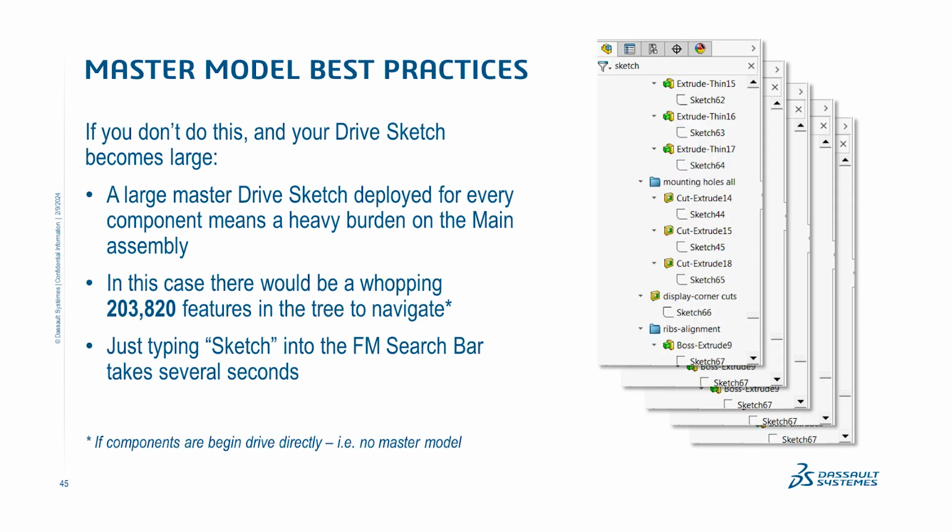The other thing about that is, if you do create that master sketch and use that as your master model technique, you have various parts in your assembly and they're all being driven by the master sketch. Well, there's a danger in that too: you're overburdening your assembly. Think about it, if you have multiple parts that are all being driven by a common master sketch, those 25 references are being multiplied by each part in the assembly.